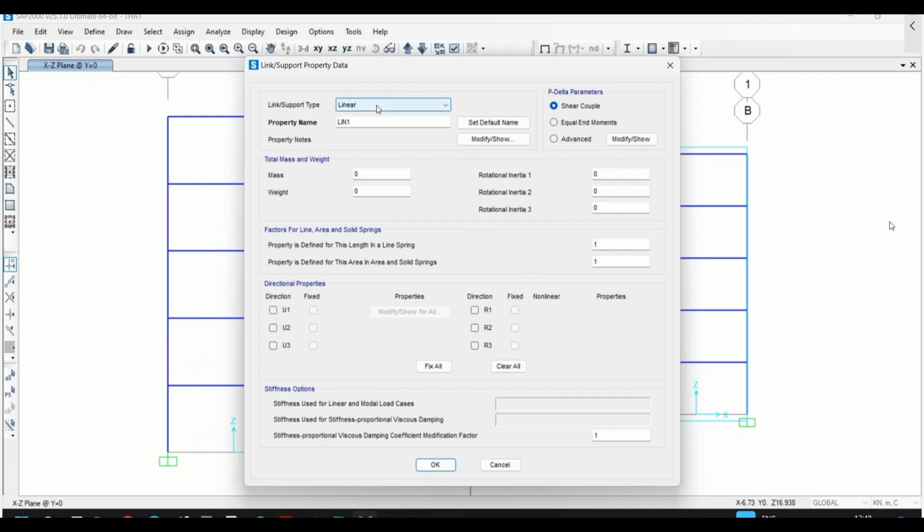And you have various types like multilinear elastic, multilinear plastic, dampers of specific types, exponential, bilinear friction, gap, hook elements, plastic, and then you have rubber isolator, and then other isolator types, friction, triple pendulum, etc. A wide range of types are predefined and available. I'll use rubber isolator for this example.